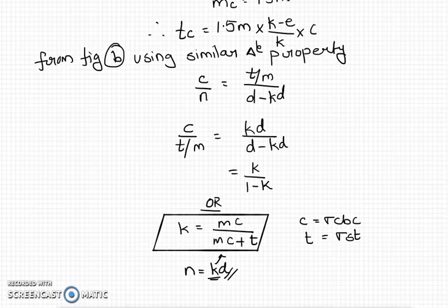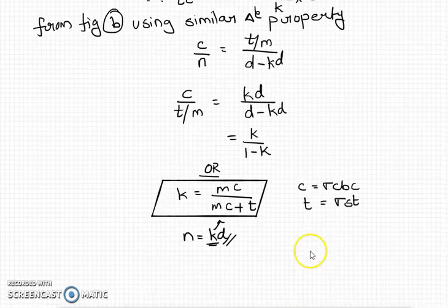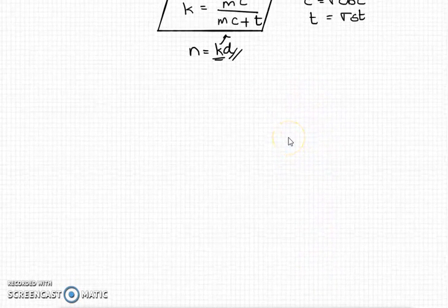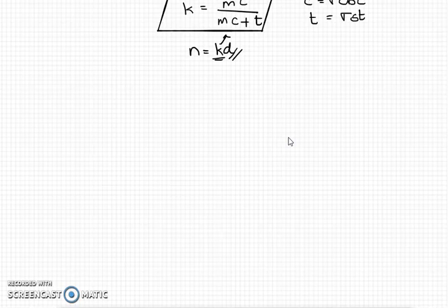Now, by neglecting the concrete in tensile zone, obviously, when we considered the singly reinforced section, we had neglected the tensile stresses in concrete. So similarly here we will neglect the concrete in tensile zone and equate the moment of compression area about neutral axis to the moment of tensile area about neutral axis. This is the same thing that we had done for singly reinforced section also.